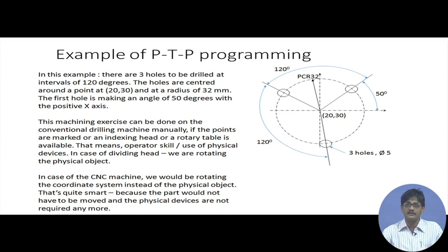Yes, we can do this in conventional drilling. How will you do that? Well, we can use an indexing head, place it with axis upright, that means vertical, on the machine table, and use a vertical drilling device to drill these holes. The indexing head can rotate, so that sequentially the hole positions will be just under the tool and the drill will be drilling them.